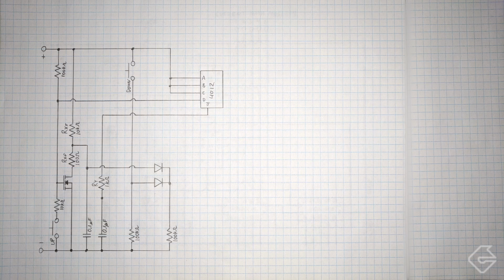And here's why. Because of the sizes of these resistors, notice this is a 10 kilo ohm resistor. In the original schematic, this resistor down here was also a 10 kilo ohm resistor. And so that creates a voltage divider when the button is pressed. That voltage divider means that this point right here at the end of the OR gate will never exceed 6 volts. Of course, that's going to be a problem. We need this to actually register a 0 or a 1 depending on what's happening here.